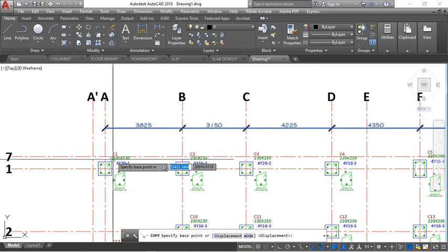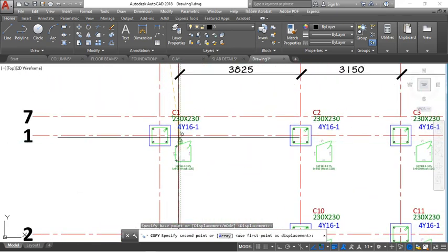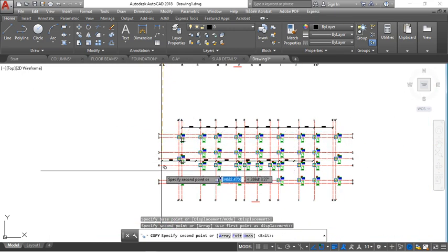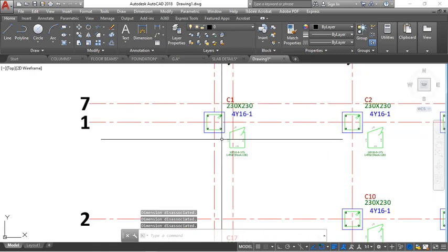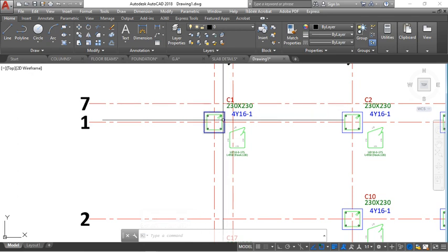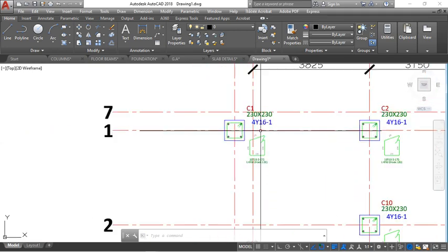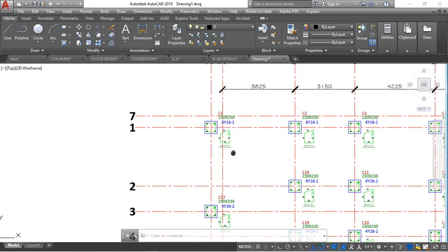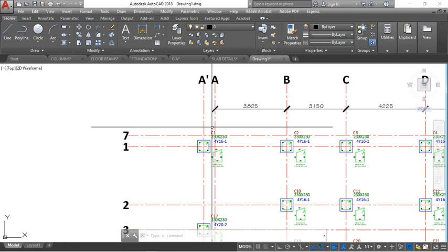For this, I want to copy this dimension to the next drawing, and if you notice, you can see that this one will not align because the column has shifted. Now, quick observation, part of why I came about using scale 1 to 8 is that you will have some cases whereby the columns will be off some grids, so you don't want a drawing that will be too big and kind of in appearance you are wondering, okay, how is this thing.